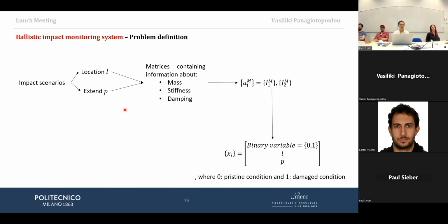due to damage. These changes can be identified by processing the acceleration signals and potentially some features coming from this signal. These features could be the amplitude and the frequency of the peak corresponding to the natural frequency of the system, or for example, in time domain, it could be kurtosis or peak-to-peak, and so on. It actually depends which method provides us the most robust and accurate results.